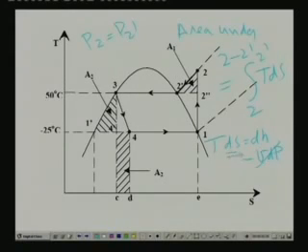So finally you find that TdS is equal to dH, that means integral TdS from 2 to 2 dash is nothing but integral dH from 2 to 2 dash, which is simply equal to H2 dash minus H2. It is as simple as that. Since we know the enthalpies, we can easily find it, and this, remember, is the entire area under the curve.